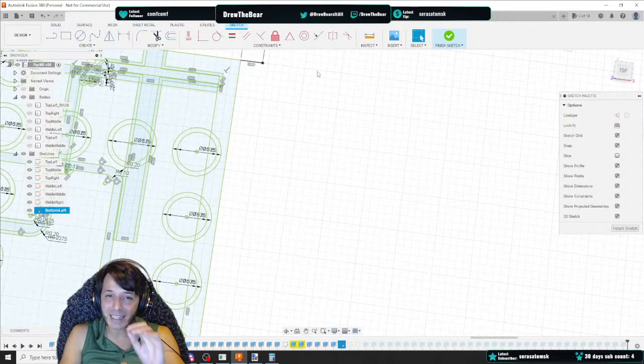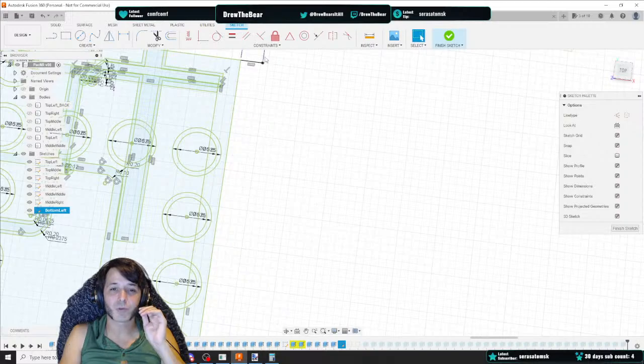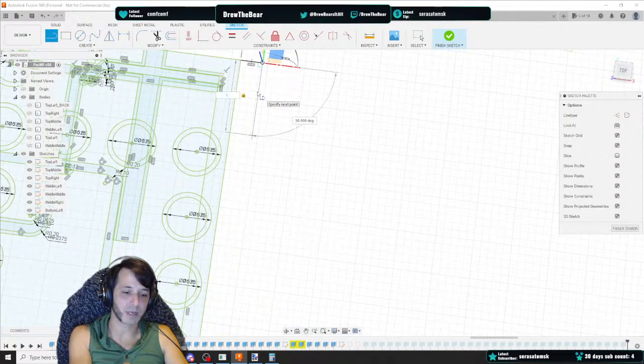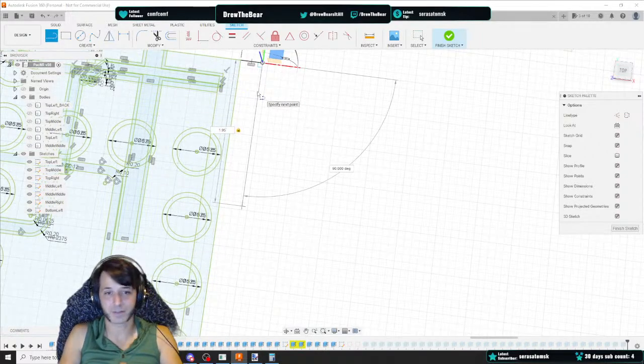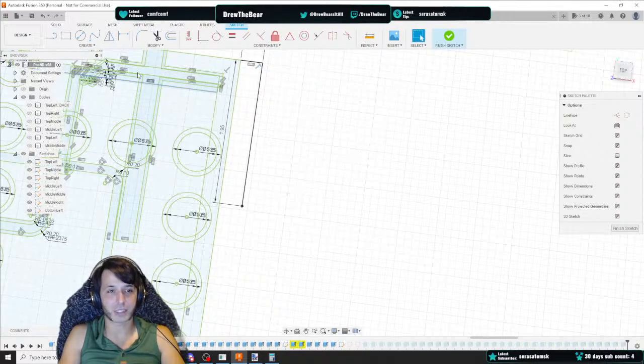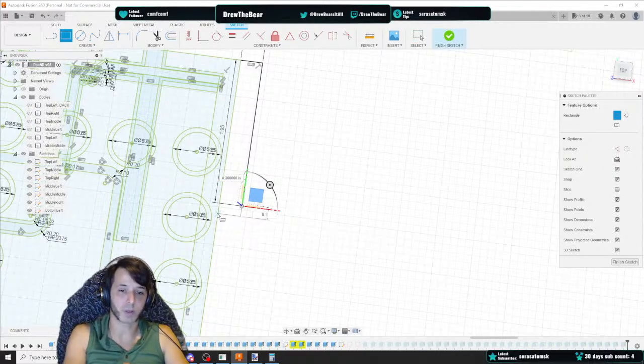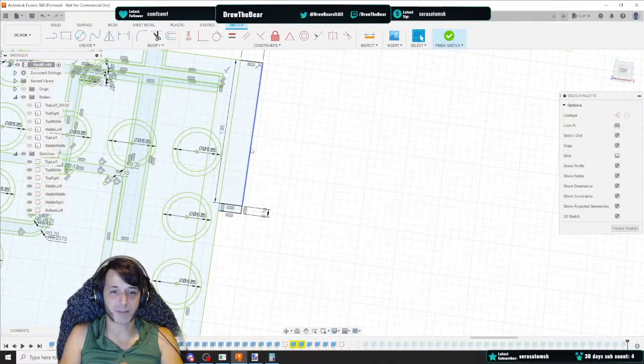It'll be just slightly off, like a number rounding error, and you don't want that. So now it's 1.95. The reason it's not 1.945 like the other is that these rods, like I said, are not 0.11 width, they're 0.1 width. Which means the halfway point is 1.95 to the wall to create the halfway point at 2.